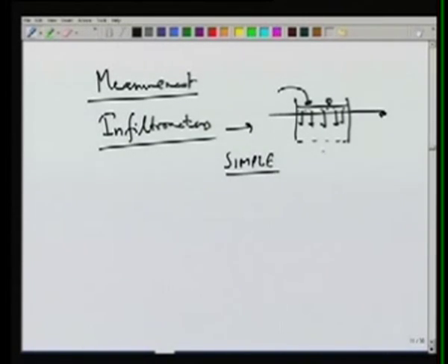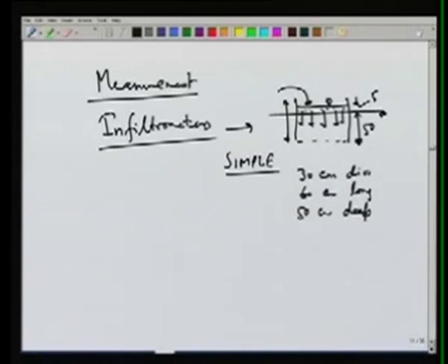Typically the dimensions of the rings are given. For example, a generally used ring may be of 30 centimeter diameter, 60 centimeter high or long, and it may be driven 50 centimeter below the ground surface, and the water depth is generally around 5 centimeters.